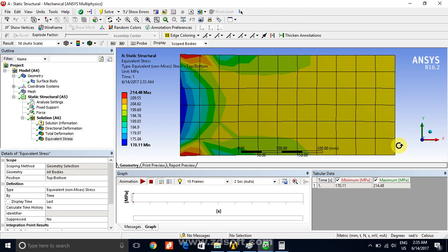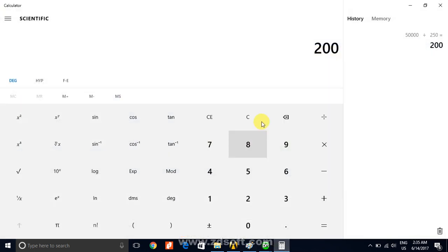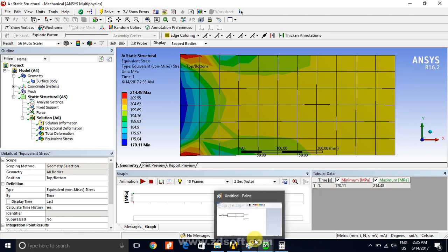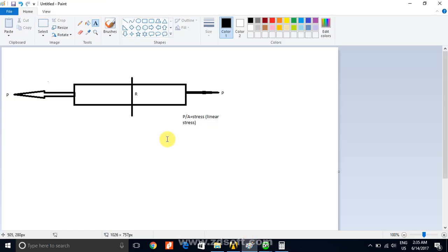From that, if you calculate, the von Mises stress is going to be equal to sigma x, and we have calculated that sigma von Mises, or sigma x, should be 200. This 200 should be throughout this body, with no color pattern. There should be no color pattern.